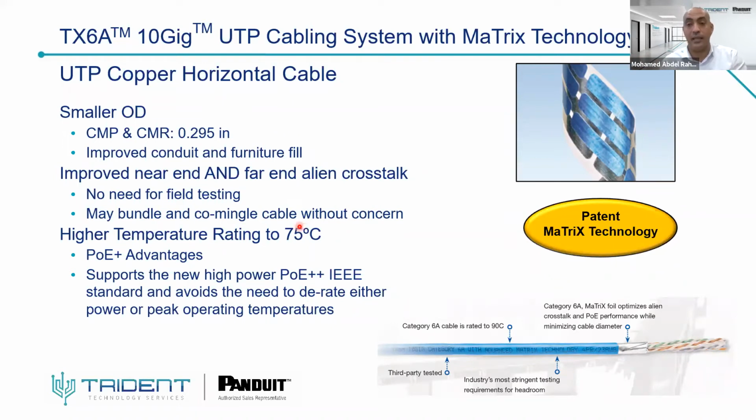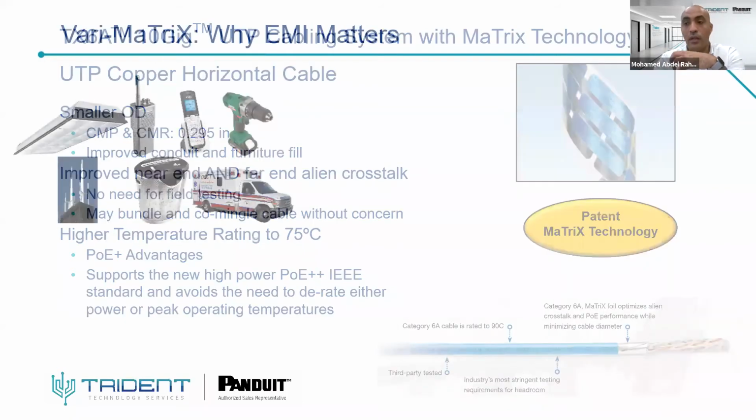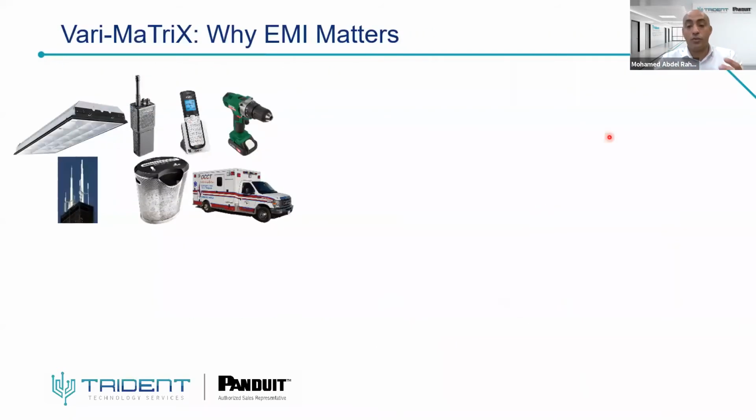We now have the best immunity to electromagnetic interference. So you have a higher performance using the UTP cable. It is a UTP solution, but with a foil cut by laser, or discontinuous foil, as we said. Now, the meaning of electromagnetic interference: these are the common sources, like light fixtures, radio and TV broadcast, walkie-talkies, or airport communications.